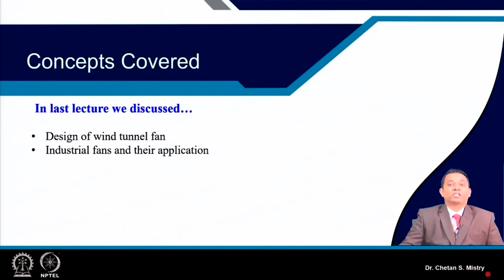As we have discussed, they are rated in terms of CFM, and pressure rise in inches of water column or meters of water column. Then we realized they operate in different operating configurations where temperature, pressure and altitude are of great importance. So let's take one design for such an application.